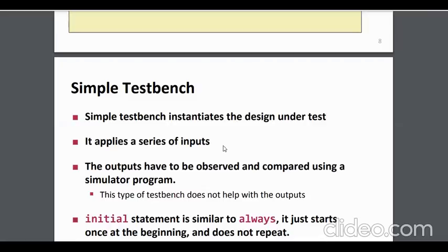My inputs will be declared as reg and my outputs as wire, because I am giving some values, or stimuli, to my A and B. They need to hold some value and then drive it to my DUT. Holding takes care of reg only. A reg is for holding or storing data, but a wire is just a connection. It cannot hold a value.